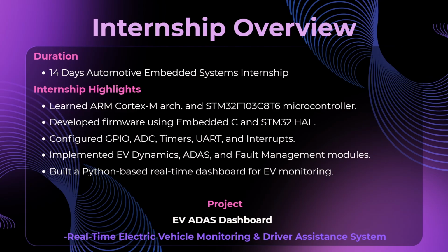This internship was conducted for a duration of 14 days in the domain of automotive embedded systems. During this internship, I learned fundamentals of ARM Cortex-M architecture and also worked with STM32F103C8T6 Blue Pill microcontroller. I also developed firmware using embedded C and used STM32 HAL libraries which made the programming much easier. As a part of the training, I also configured the important peripherals such as GPIO, ADC, timers, UART, and interrupts, which were essential in embedded system development. Finally, all the process data was displayed on a Python based real time dashboard, completing the project.